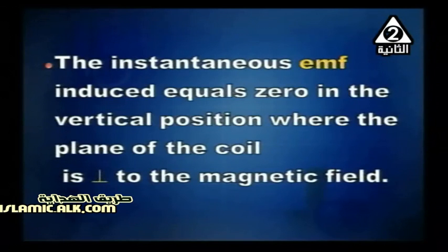Instantaneous EMF induced equals 0 in the vertical position, where the plane of the coil is perpendicular to the magnetic field. Okay, but the sides of the coil, the limbs of the coil, move parallel to the field, so there is no cutting, so no EMF is induced.